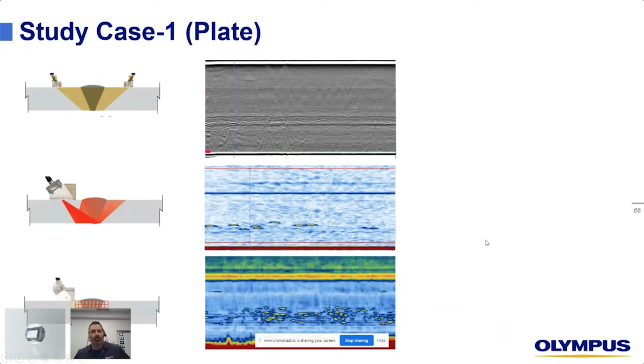So here's a summary of the same zone viewed by 3 different methods. So going back to the theory before, what we would do is first screen with TOFD, adjusted gain, contrast, and brightness also, to maximize our detection of HTHA cluster or colony. Then go on with phase array or TFM to actually further confirm and size those indications right there.